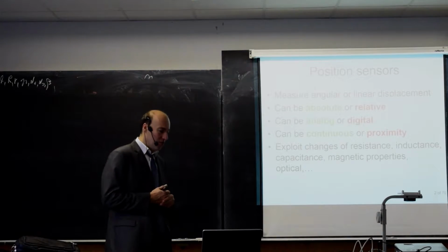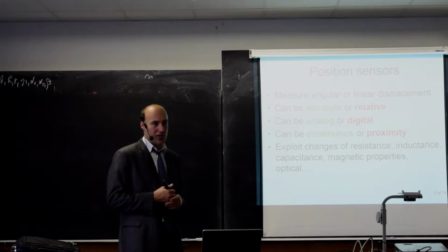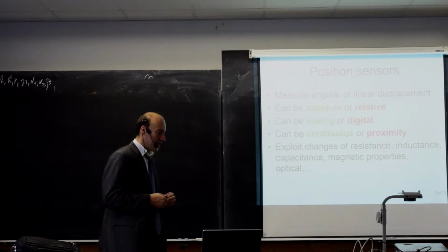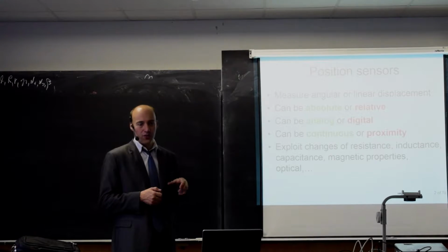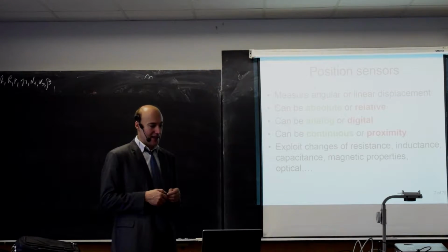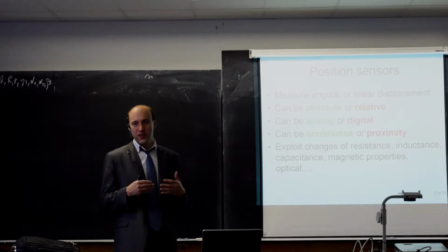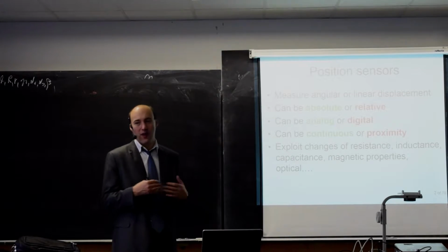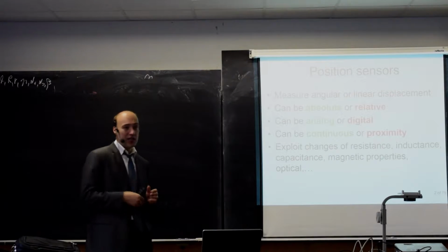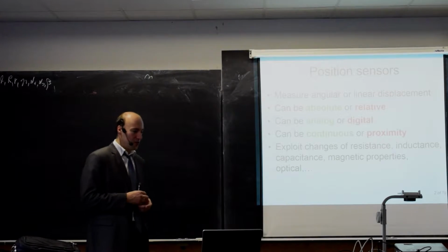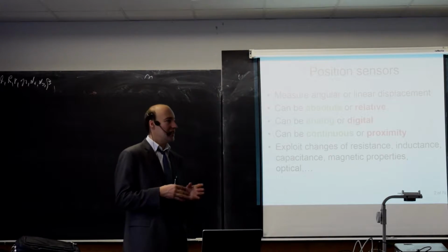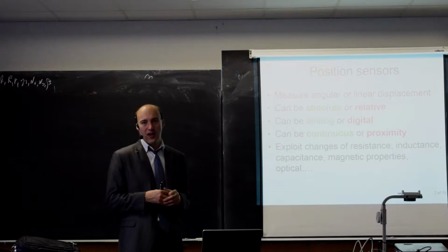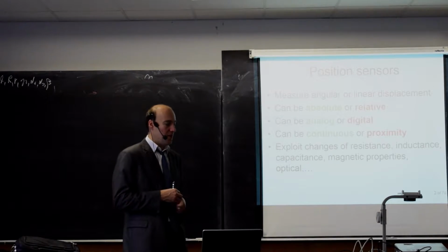So if you use a position sensor in this kind of application, the sensor is sensing the position of the shaft of the motor in order for the algorithm to work. And there's no way you can make a reference movement. There's no way you can move the train forward and backward a little bit. So you need an absolute sensor for this. Absolute sensors are good for applications where you cannot do this reference movement. You need directly the correct position information after you start the machine.